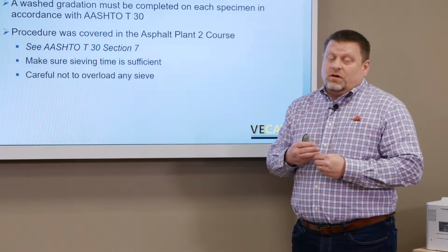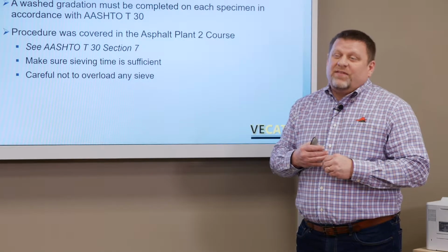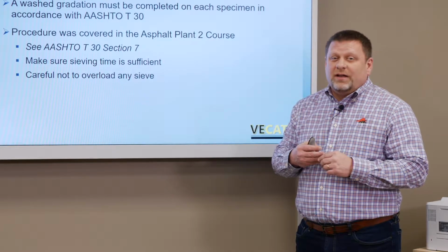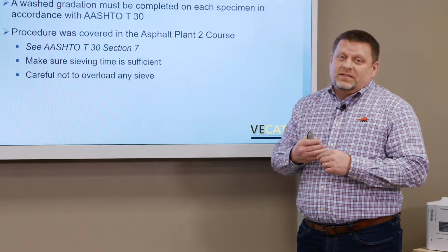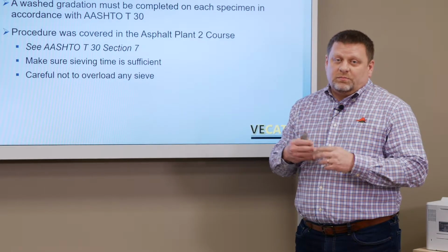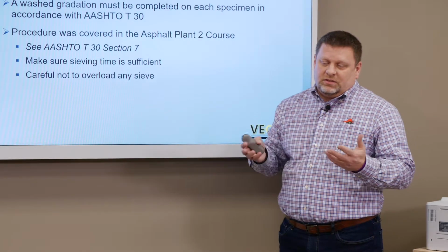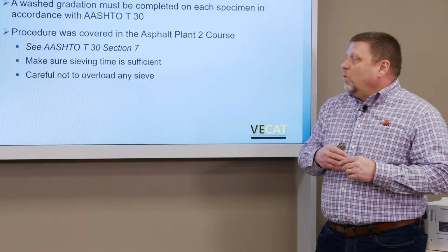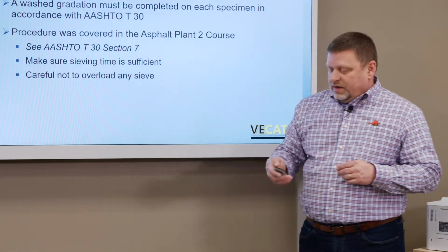And I've used those for 20 plus years, and I found that to meet a proper sieve time, I had to usually run about 13 minutes instead of 10 minutes, just due to the different process and how it does its sieving. One other thing I want to talk about is not to overload any sieve.